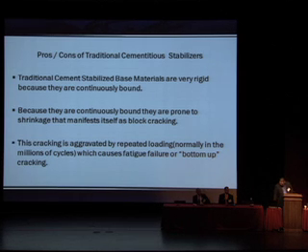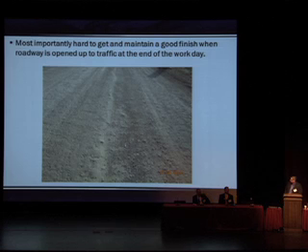Another problem that we've seen with them is the inability to get a good finish. We've got some contractors that do 4 transports a day. They'll do 2 transports in one direction till about noon, and then switch traffic and do 2 transports on the way back. They're very efficient at it, but because we don't allow for proper curing, our roadway surface suffers for it.